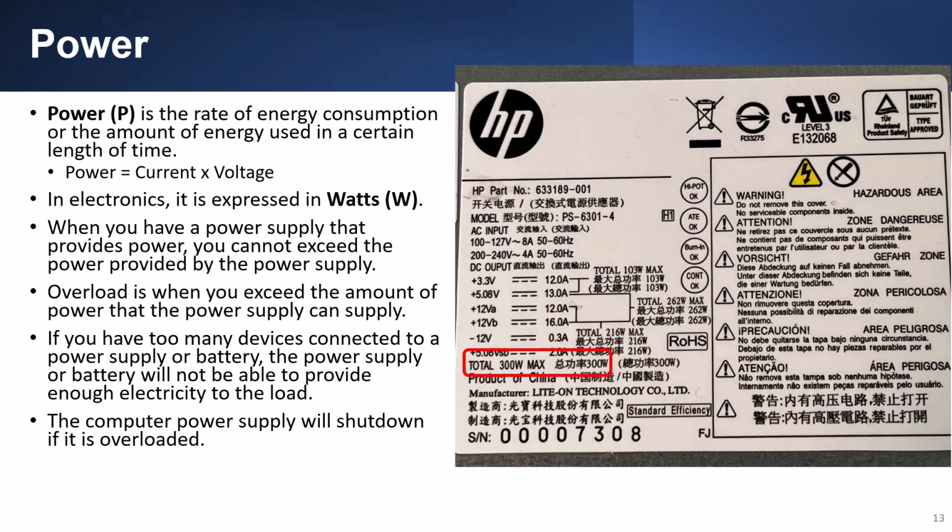On occasion, I will look for the amount of wattage a specific device uses, and the information is not readily available. In these situations, I will find the voltage and amperage rating or current of the device, and I can calculate the power consumption by multiplying these two values together. This will not be on the A+ exam, but it can come in handy.